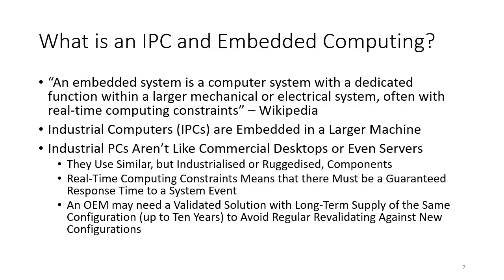Sometimes the embedded computer could be a PLC, a programmable logic controller, so that's a specific category of industrial PC, and I won't refer to that too much, although today if you do look at a PLC you'll see that some of the architectures are similar to industrial computers. But more likely an industrial computer will be used for something like data collection, possibly for local HMI SCADA, maybe for doing some higher level control above the PLC, such as an advanced algorithm for optimization of control. But ultimately, it's all part of the larger machine application.